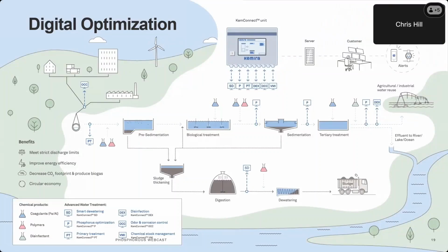Thanks, Richard. The sustainability of phosphorus removal through chemical treatment can be enhanced using digital automation. Optimization of coagulant dosage can be tightly controlled through this emerging technology. Ultra-low phosphorus limits require high ratios of iron coagulant. Therefore, precise continuous monitoring and dose control is essential to managing cost and resource consumption. This becomes especially important when facing water flows and quality variation due to storm events and industrial contribution.